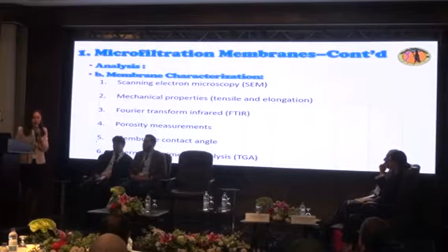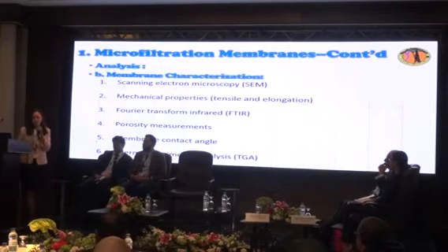The number of pores should be higher than the usual membranes, just to prevent the clogging of the membranes at any time, because you are in an oily industry, so you need to focus on the pore size and the pore density. And also the membrane contact angle, to know the membrane hydrophilicity, if it will pass the water or pass the water with the traces, to make sure of that. And the thermal gravimetric analysis, which is the thermal transition temperature of the membranes.